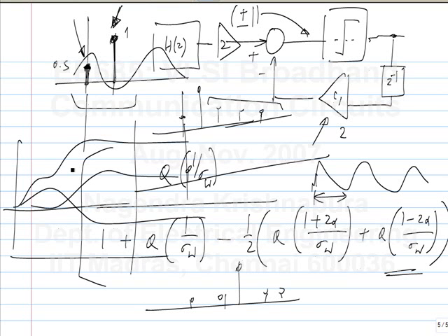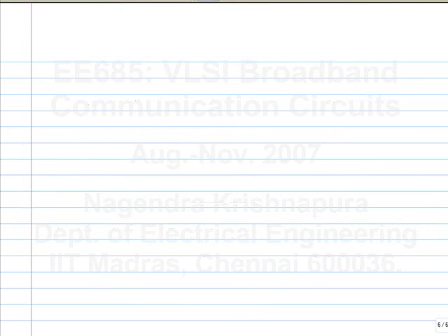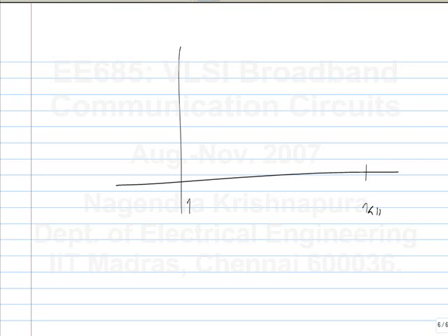So one thing I have found in many assignments is you don't use the axis range properly. Here we have not dealt too much with frequency response, but the typical frequency response I see will be plotted from 1 hertz to 1 gigahertz. The action is somewhere between 100 megahertz and 1 gigahertz. So the plot will look like this, and this will be 0 and this will be minus 300 dB. So basically you can't see anything. So you just cut off all the non-essential details and show the necessary ones.